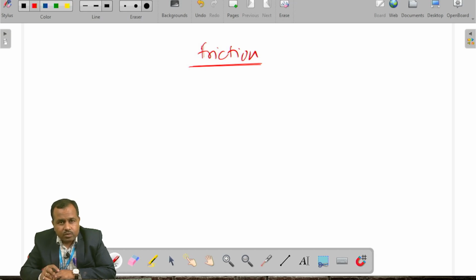There are various types of friction in moving bodies. Sliding friction is where two objects slide over each other. Rolling friction is basically observed in the case of wheels on a flat surface. Turning friction is the friction observed in links with turning motion, like one link turning about the axis of another. And there is one more, called static friction, which is the friction experienced by a body which is at rest.